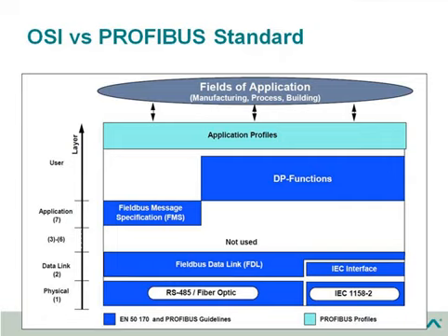In this figure, you will see that PROFIBUS only uses Layer 1 and Layer 2, as well as the user interface. Layer 3 to Layer 7 are not used. This streamlined architecture ensures fast and efficient data transmission. Above Layer 7, PROFIBUS defines DP functions available to the user, and the system and device behavior of the various DP device types are specified in the user interface. Starting from the next slide, we will introduce the PROFIBUS standard from physical layer to user interface.